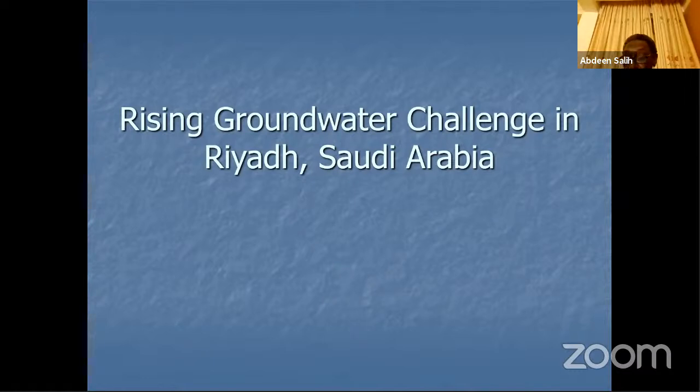When I went back to the University of Khartoum after my second month, there was a great period of drought. This wadi has alluvium aquifers, and the alluvium in its maximum part is about 40-something meters deep. But this alluvium aquifer used to give the whole city, when the number of people was small, their domestic water, but it also irrigated a chain of gardens along the wadi within the framework of the city. What happened when I left in 1986? There was a drought. All this alluvium became 100% dry. So to get water for the farms of the people, they had to drill to the Minjur aquifer, which is about 1,000 or 1,200 meters down. In fact, the water comes from that level very hot, so you have to cool it before you give it out, a very expensive exercise.